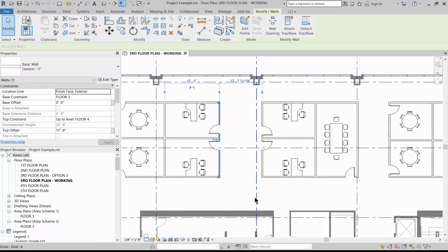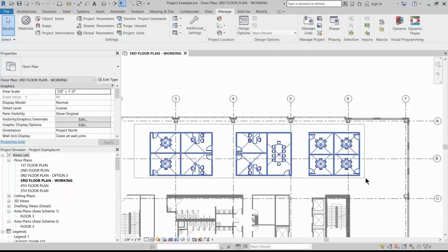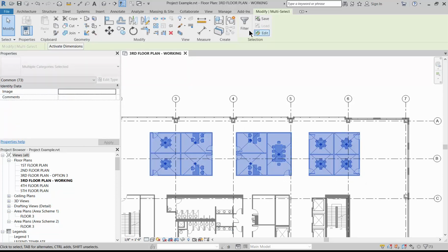And if you were drawing this appropriately, you should have selected the generic 5-inch wall, which is the most typical thickness of the partition. And also at this point in time, look at the height. Think about your ceiling. If you're doing ceiling height, through ceiling height, you should be thinking about defining heights of all of these walls. So what I'm going to do first is define all of my walls in this area as a certain height.